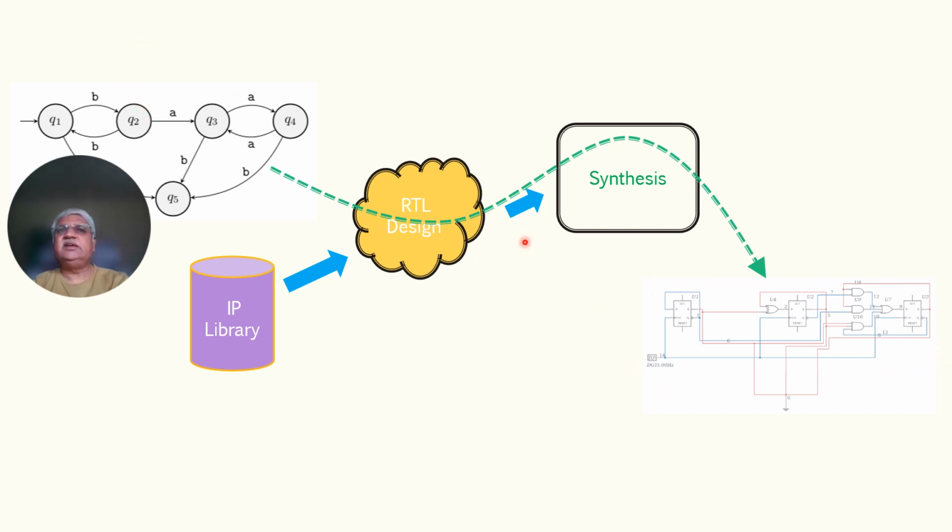So this design is made into register to register transfer. Here one register is transferring data to another register. The data taken from this register is picked, some logical operations are done, here it is XOR, and then it is stored within this register. That is why the design implementation in this phase is called RTL design.